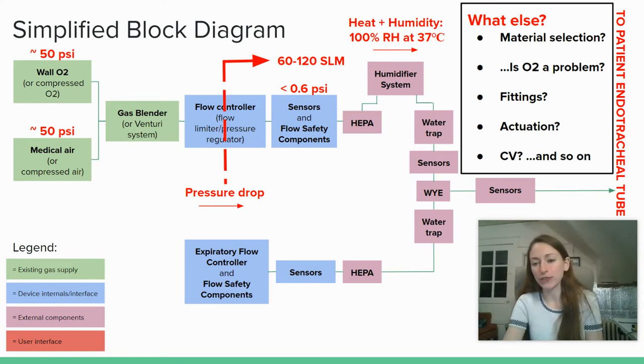You need to spec for which fittings you want to use within your device. So I try to select valves which give us 1/4-inch NPT fittings as a standard fitting. You need to understand how your valves are actuated. Some of these solenoids may require pressure drop assist. So if you're operating within this really low pressure regime, your valves may not even open the way you expect them to if they were a zero pressure drop assist.